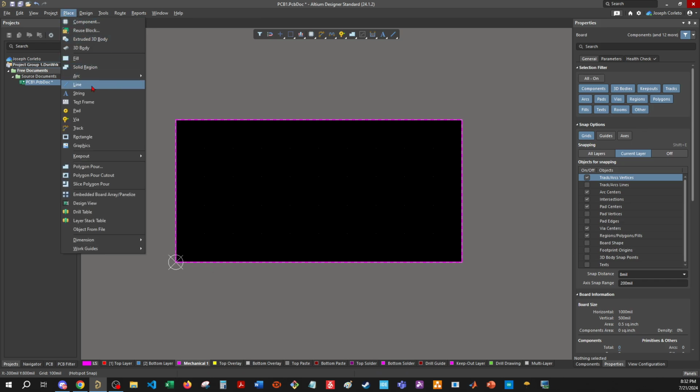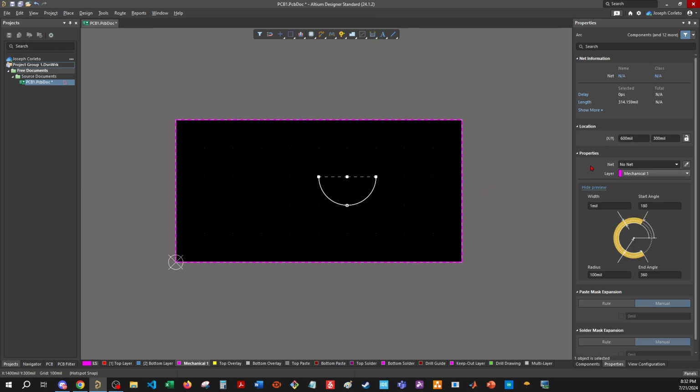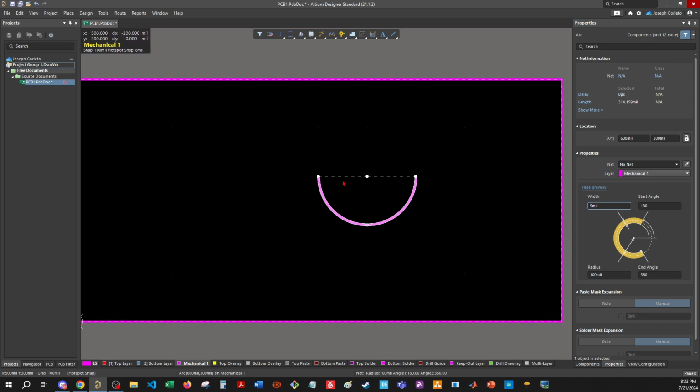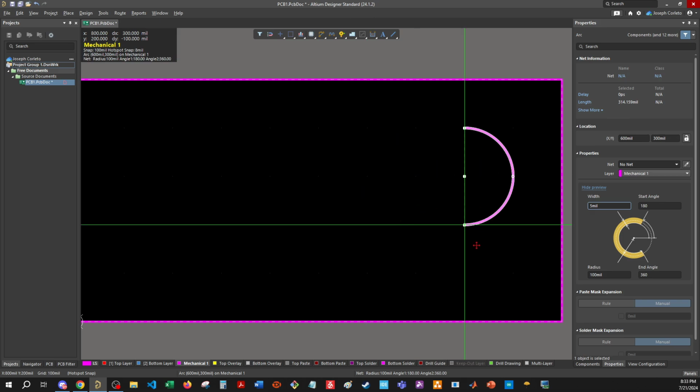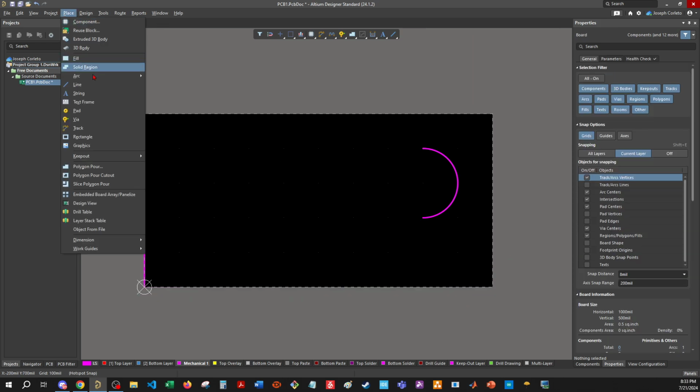You can go ahead and use things like, let's say, an arc, center. Click the center, left click once, left click again, one more time. We've got an arc here, right? Let's make this arc 5 thousandths like the rest of the board. And let's rotate this, let's say like this, right? And we're going to delete off these pieces here. Let's place a line.